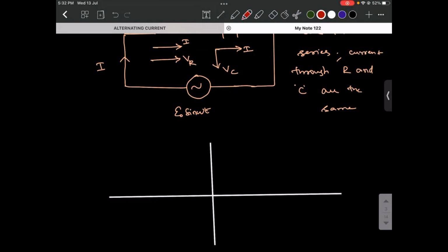so when I say phasor diagram is mainly used to draw the quantities which are represented as sinusoidal functions. So here there are two quantities. One is VR. So if I take VR to be like this, then how is VC with respect to VR? 90 degrees. 90 degrees in which direction? Is it leading or lagging? It is lagging. In the lagging sense, VC will be here.